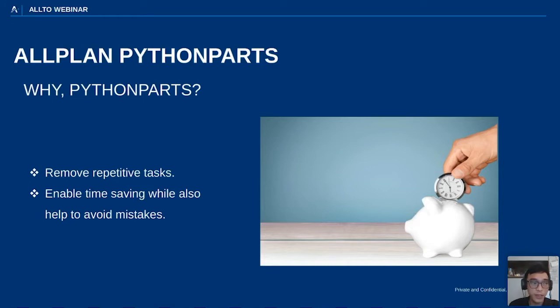For freeform objects, you can use the new parametric 3D modeling functions. Interaction between individual Python Parts, and between Python Parts and other ALLPLAN objects, is also possible. And with Python Parts, the scripting of reinforcement is far more efficient. With the help of the reinforcement set builder, you can automatically generate many sets using CSS and concrete cover.